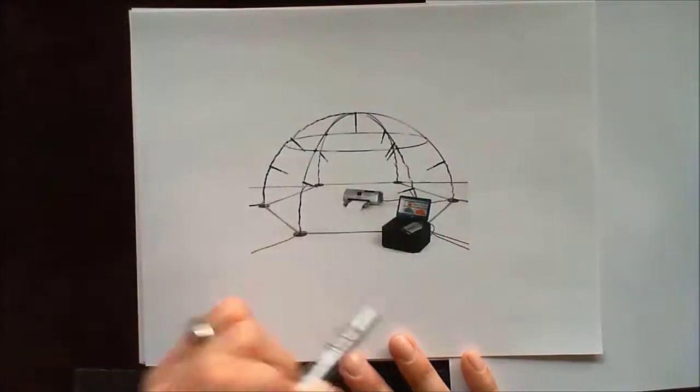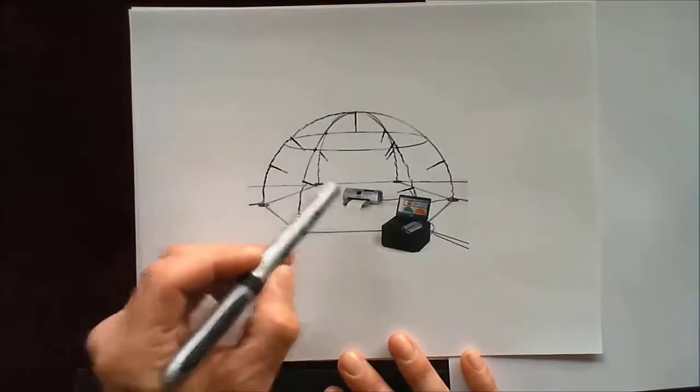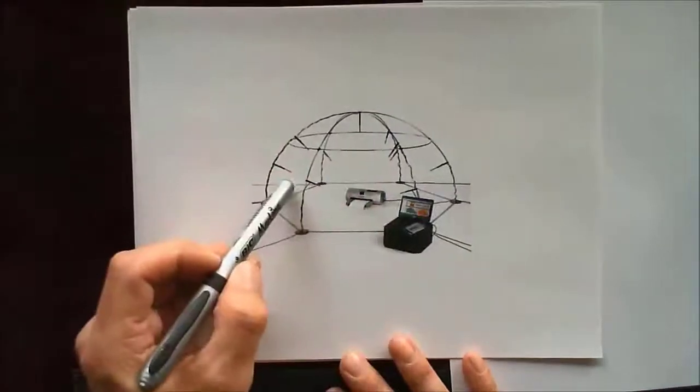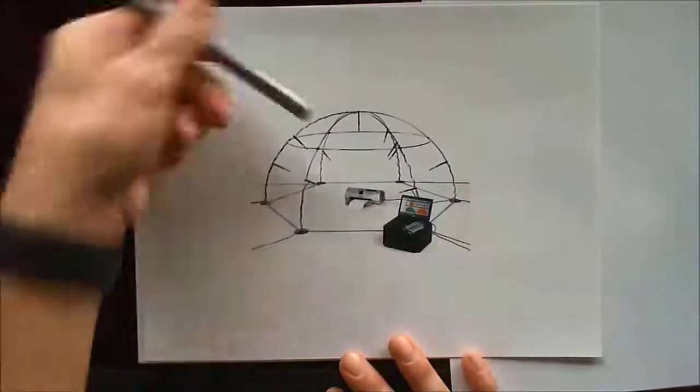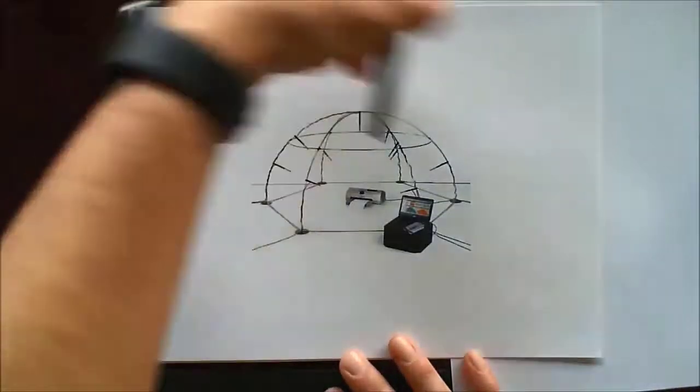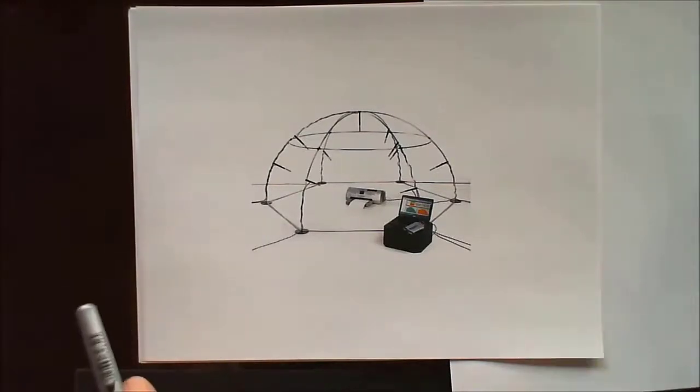Okay, so when we're summing up all these microphones, and sort of averaging them all out, this is giving us the ability to take the sound pressure measurement on average for the whole object without regard for the location of the measurement. If the microphone's up top, on the left or the right, we are going to average all that out, and so we get a loudness or a sound pressure without respect for the location.